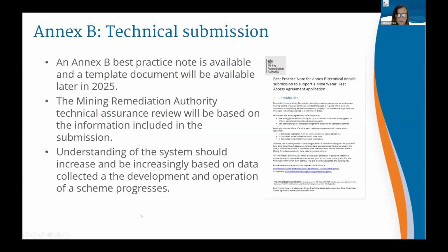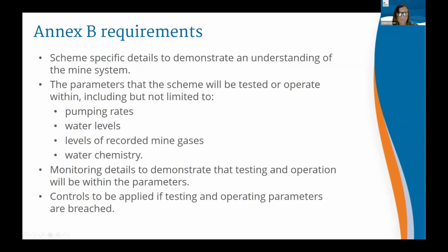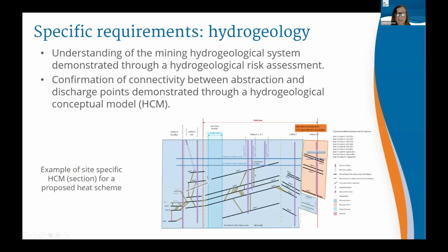As the process goes on, the understanding of the system will become more based on the data and less based on historic records. The parameters of the scheme will be tested. They're not limited to pumping rates, water levels, levels of recorded mine gases and water chemistry. I've mentioned the monitoring details to understand the parameters, and again, how that's monitored, not just within the operational boreholes but within the system, and what controls will be applied if those parameters are breached.